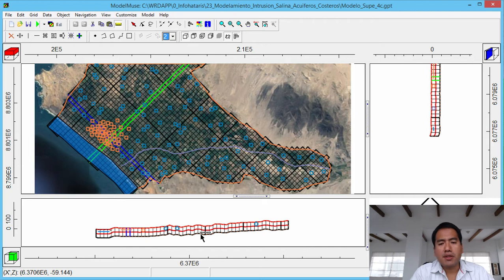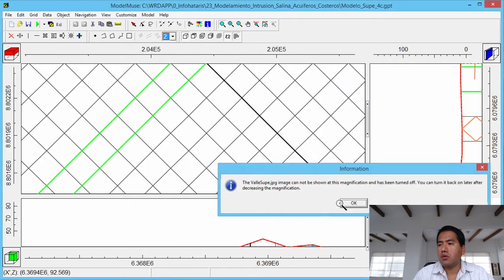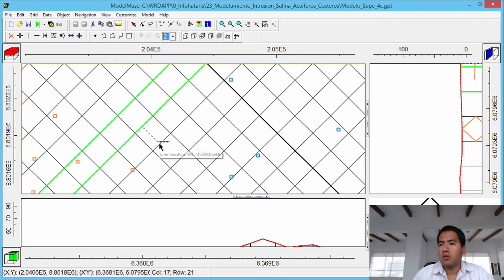You will see the limits of this while working with MODFLOW and this Seawater Intrusion package, because you will have an interface for each layer, and sometimes those interfaces are not quite exact. Okay, cool. The horizontal discretization is 200 by 200, so each cell is around 200 by 200 meters.